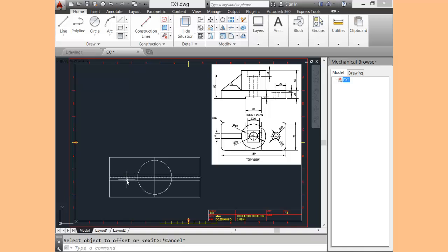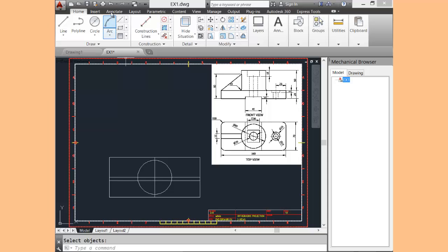So these two lines are representing our web, but our web is not along the base, it's only to this circle. So we have to cut a piece of these two lines. We'll go to modify again and introduce our two commands. Erase command, select object. If we select this object and click enter, we erased all the object. Go back, undo. We don't want to erase it all, we want only a piece of it.